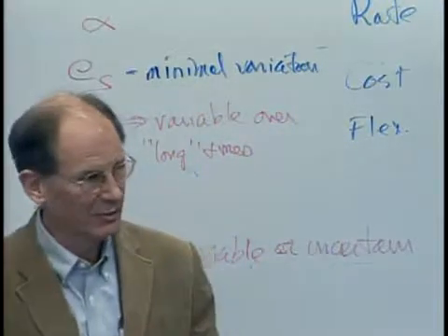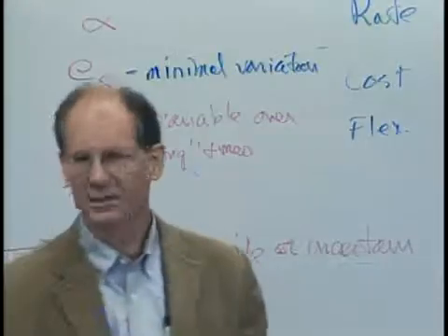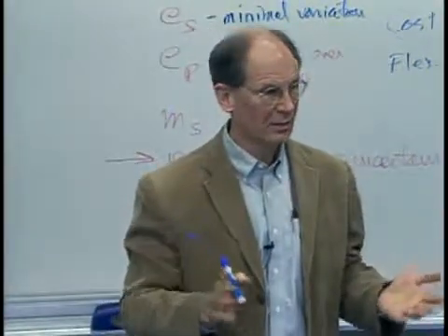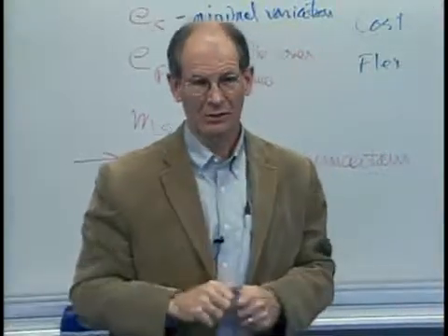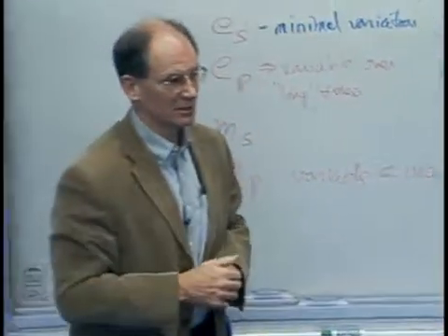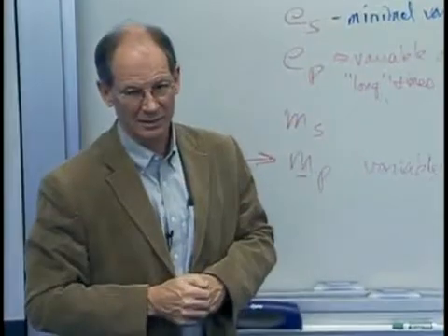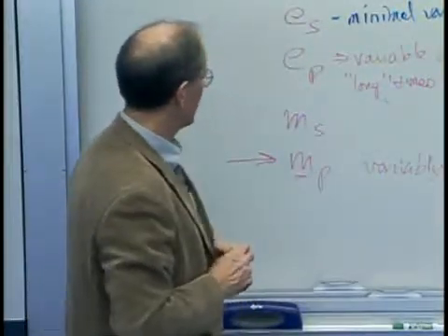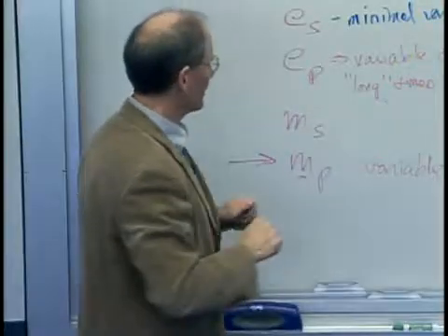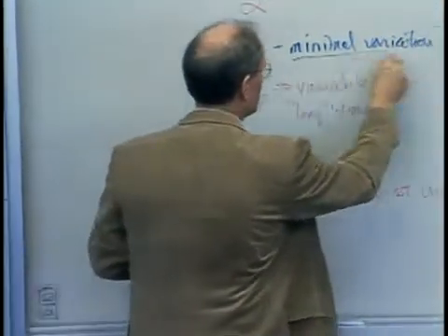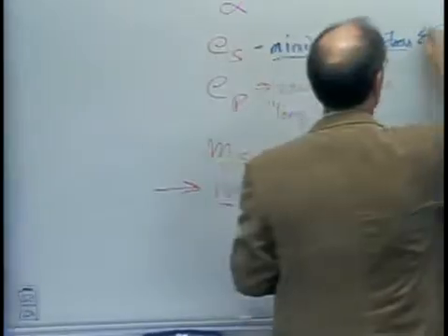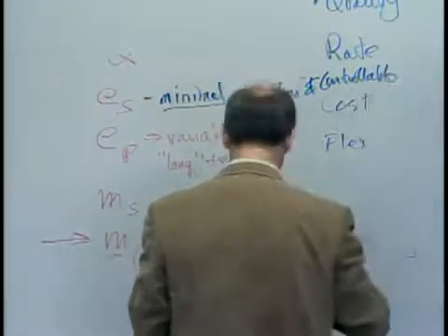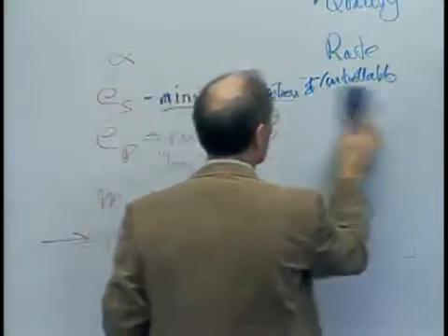I know exactly. If I have a good servo and I say go to this velocity, it goes to that velocity. If I have a good temperature regulator and I say go to this temperature, it'll hold that easily within a degree, and in some extreme cases a lot less than that. So particularly with the use of active control, we've made that really good. So the last one, and I would say controllable. In other words, not only is it not variable, I can actually tell you what I want it to be.